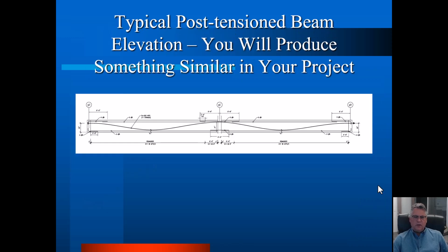So this is a typical post-tension beam elevation. And since you're the paying customers in this, the end game in this class, at least for the first 10 weeks, is to design exactly everything you're looking at. You are going to do a 2-span beam. I'm going to give you the drape and profile because I don't want to grade 30 different designs, but once you have that, you're going to verify everything by hand, all the stresses.